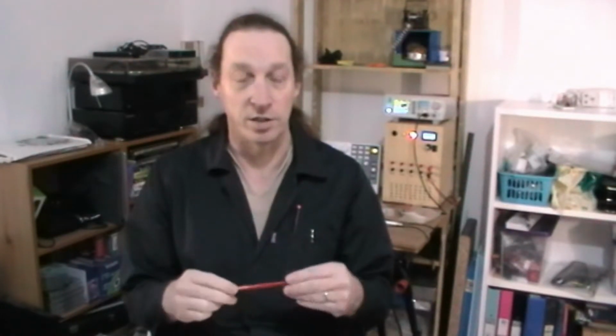I suppose what you could do with that is try to narrow that bandwidth. If you used specific capacitors, worked out what the midpoint was going to be, and then used the right values of capacitors and resistors, you can get the frequency cutoff points as close to that center point as you want, until you get quite a narrow bandwidth.